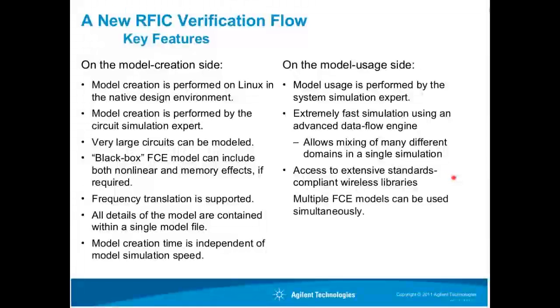And you're not limited to one model. You have the flexibility of, maybe in some cases you would want to model the whole circuit as one piece, or you could mix and match. So you could have each block modeled independently, and different blocks can be at different levels. You could have maybe a top-down behavioral model where the design's not done, and have another block that's verification, but you could have all the verification blocks in place as well. So you're not limited to just one model. And you're not limited to just one type of behavior too. One could be an FCE model, and you could have other models coming in from other sources.